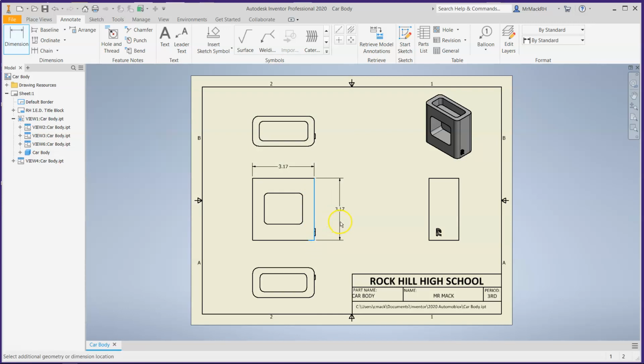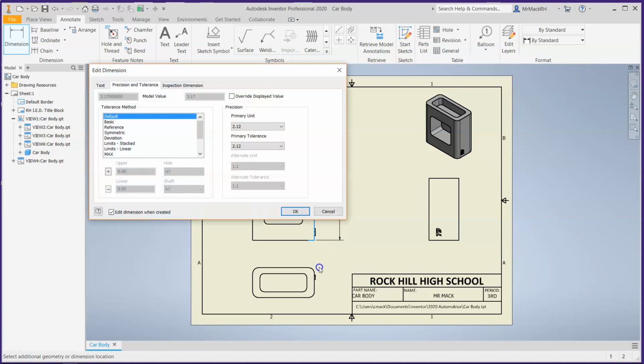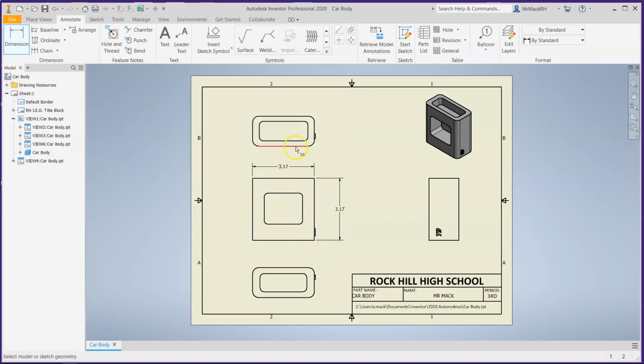All right. I'm going to pull that back one notch. There we go. So now I can hit escape if I want to move some things, if I want to adjust their position. You hit escape and get out of the dimension mode. All right. The reason I'm doing that is now inside here, I'm going to put my chain dimensions for this to this.